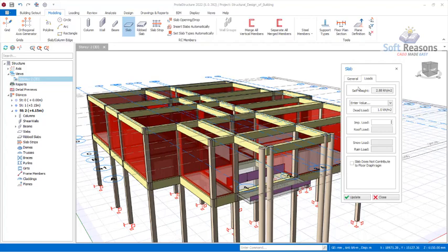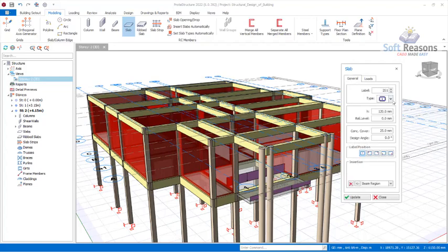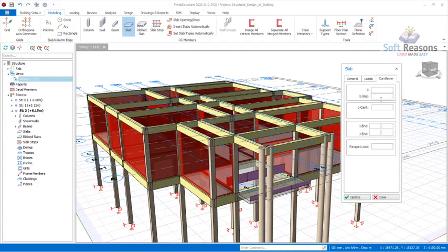So what you just have to do, get to these provisions and then get this slab type 12 right there, after which you can get to the cantilever and then give a distance. It is basically 600, sometimes 450, so it all depends, but we use 600 for the sake of this design. So for the parapet loading, we can assume it to be 5 kilonewton per meter run.